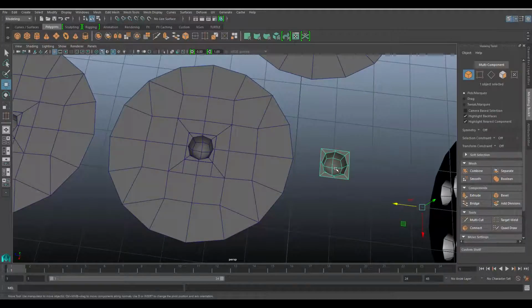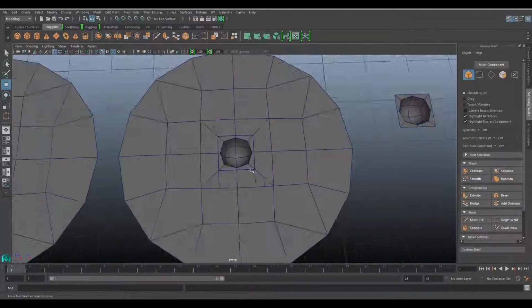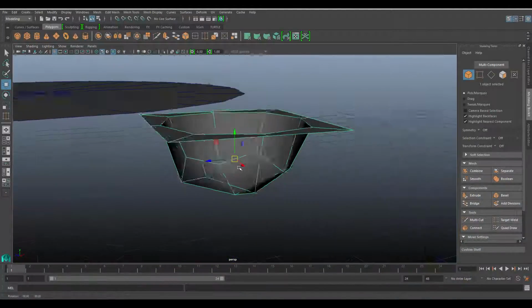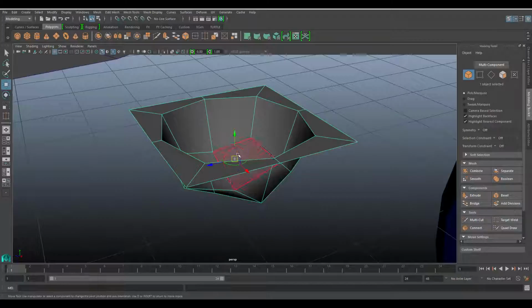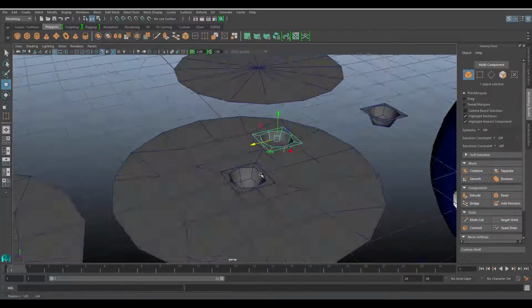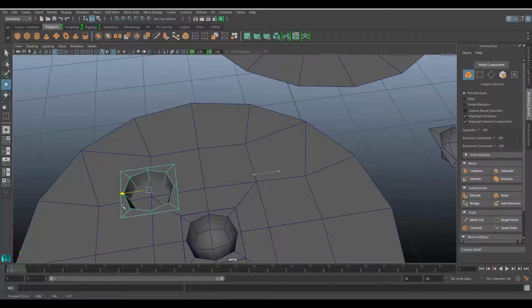There's a few minor tweaks I need to do to the single divot. But one thing, let's fix on our template here. In order to get this to center upright, what we need to do is move this pivot point so that it is as high as the rim, but still centered with that center vertex. So what I want to do is hit the D key to bring up this little thing here, click on that top, and then middle mouse drag over that vertex. And what that'll do is give us this hovering pivot point that will then snap perfectly with our caps